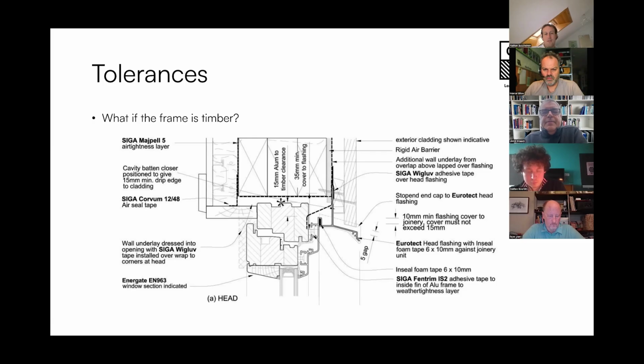10 millimeters. Oh, 10 millimeters, yeah. That's pretty much it. And imagine when you go to different materials, the wood may be adjustable on that level. But if you go for a concrete structure, regulations allow you, Marcel, 3 centimeters on 5 meters. Yeah, kind of, plus and minus 3 centimeters, which is a lot. Which means that the window changes a lot by size.